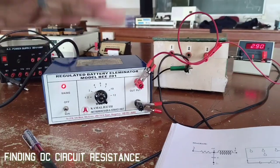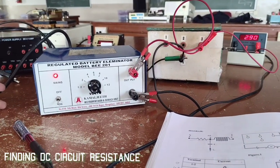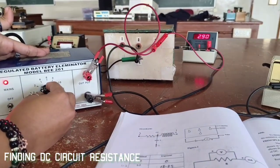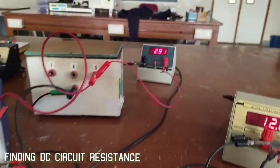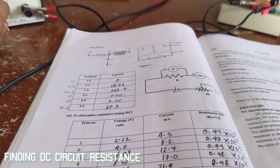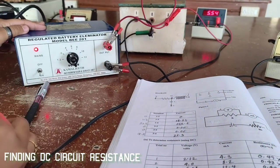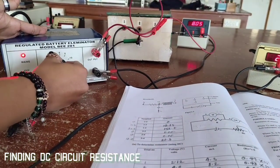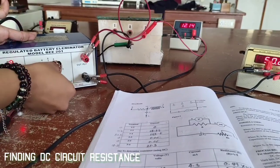So this circuit will also be in DC because Ohm's law is for DC circuits. So we start with 2 volts, and for 2 volts you note down the readings of the voltmeter and the ammeter in the table. Then you just change the voltage in the battery to 4, and again note it down, then 6, then 8, 10, and 12.